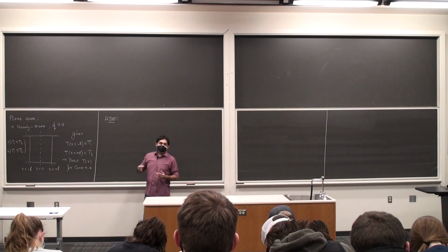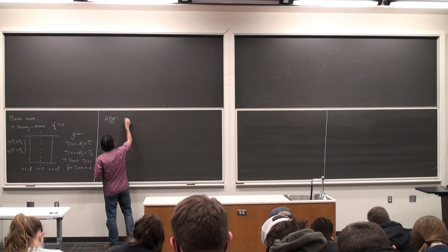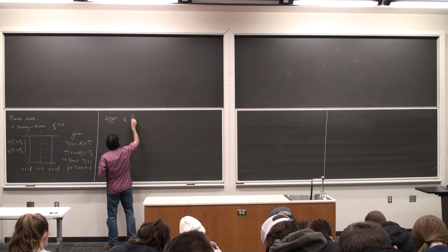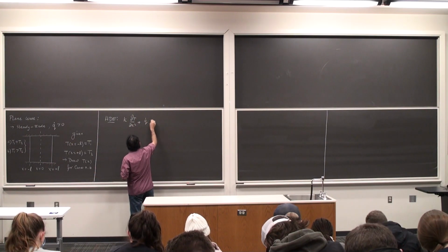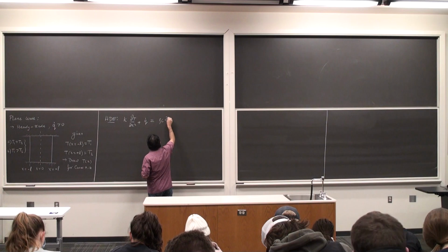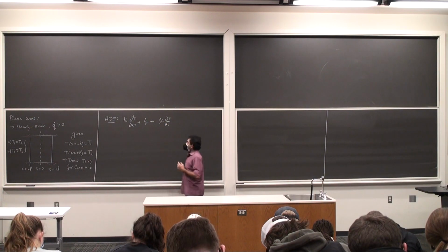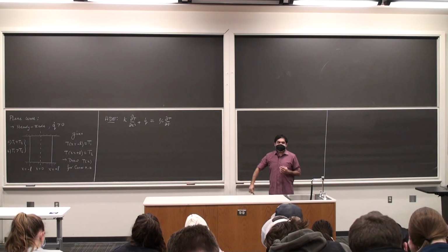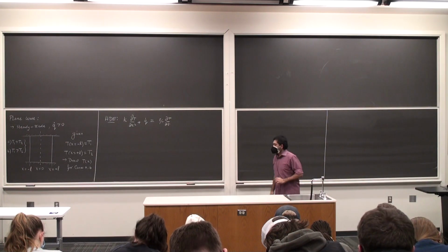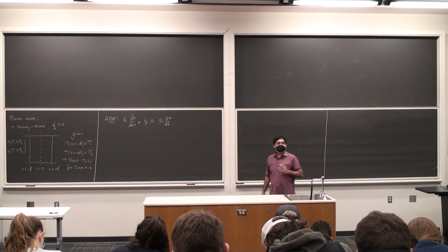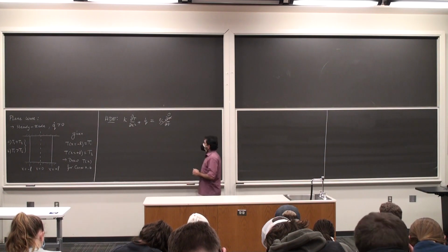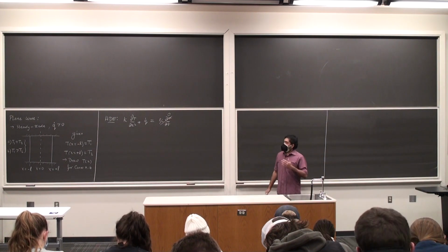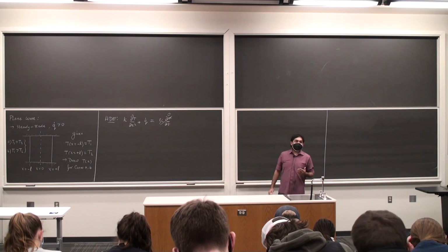So heat diffusion equation 1D. I typically write out the full thing. Okay, d square T by dx square plus q dot is equal to rho c dT by dt. This is all regular stuff. We are at steady state, so the dT by dt term goes off. Okay, steady state. And now my partial differential equation becomes an ordinary differential equation.